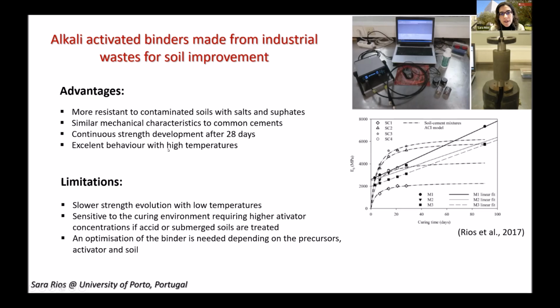And also, we have tested them at different temperatures. If we want to apply them in geotechnical engineering problems, we need to use them at room temperature or air temperature. But the difference between climates and seasons has a significant influence. For example, if we test them at 18 degrees or at 40 degrees, that changes a lot the stiffness and strength that we obtain with these materials. So they are more suitable for hot climates, I would say.